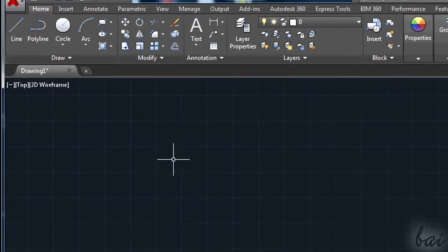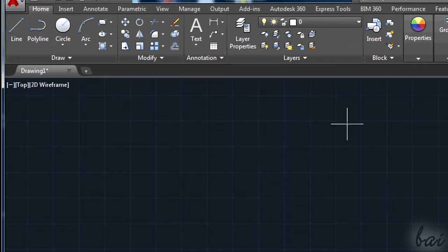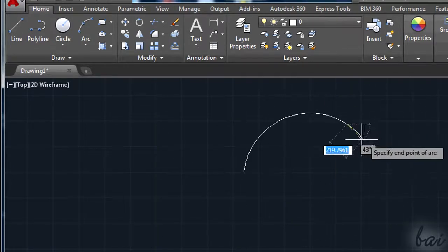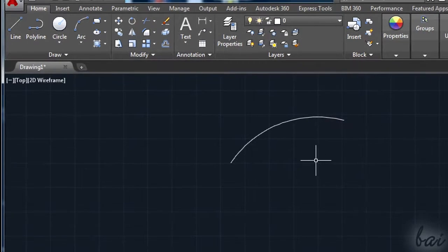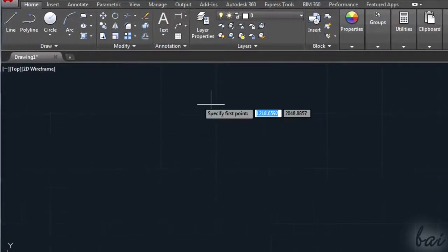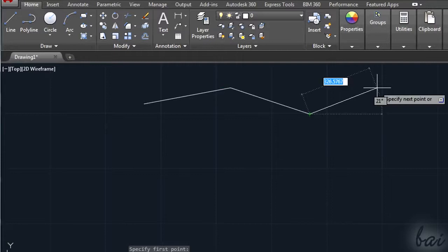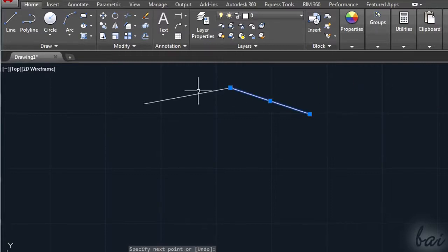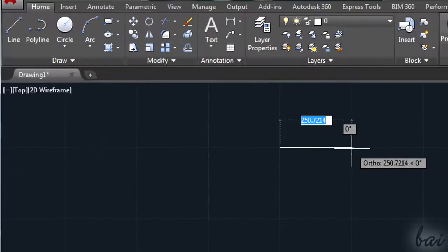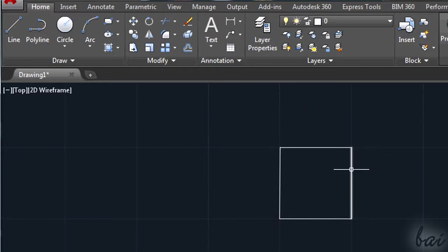When you work in 2D, you have different kinds of objects you can draw. The circles, ellipses and arcs are drawn once per time. You have to press Enter key to enable these tools again to draw another object. The line is a straight segment, but unless you press Escape key, you will go on drawing segments sharing one same node. You may build a polygon in this way, but if you analyze it, the different segments stay independent.